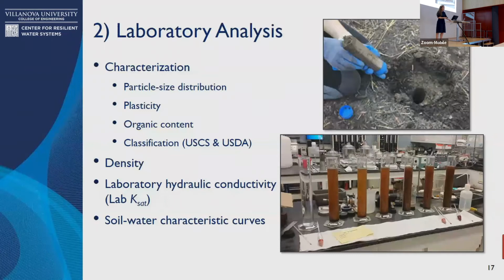So we took all of our soil samples and we brought it into the laboratory. We started looking at the soil a little bit more to try to understand, is it changing? Is it staying the same? What's going on here? So we looked at our particle size distribution, the plasticity, the organic content, the density and the KSAT through hydraulic conductivity tests, and also the soil water characteristic curves.